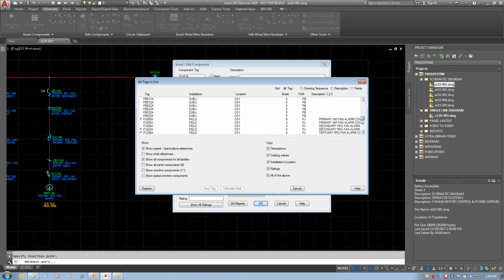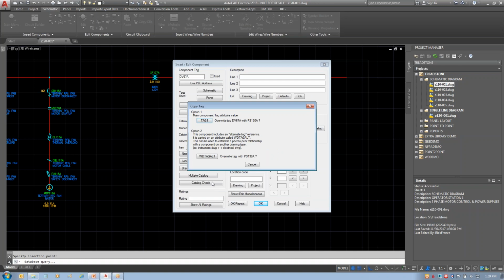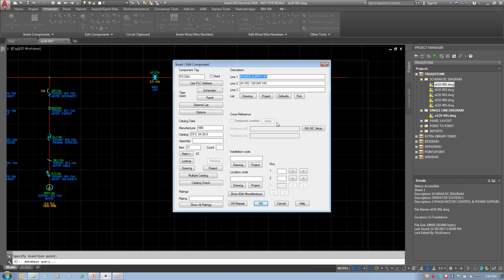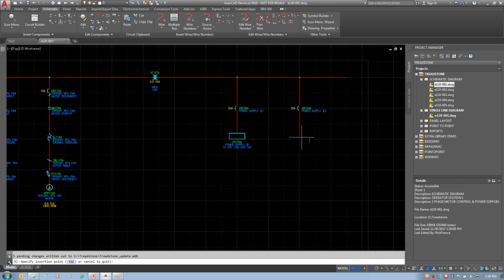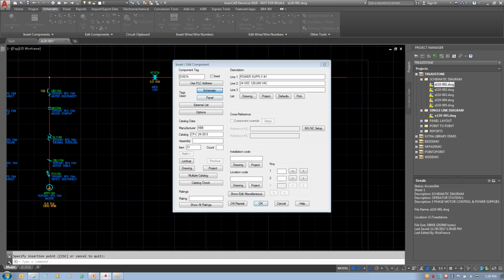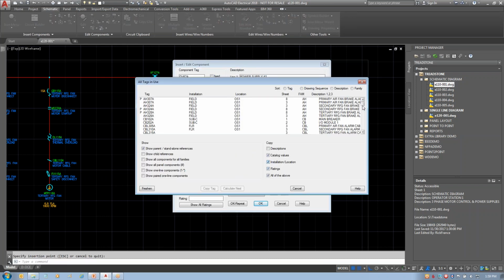In this particular case, I want the power supply. So I'll come down here. There's my power supply right there. We'll copy the tag. Same thing as the motor. It's got a peer-to-peer coil pins alternate tag there. So we're going to use tag 1 on it just like the others. We'll go ahead and say OK repeat, task it, and place this last one right like that and connect it up. Don't have to check the box again.